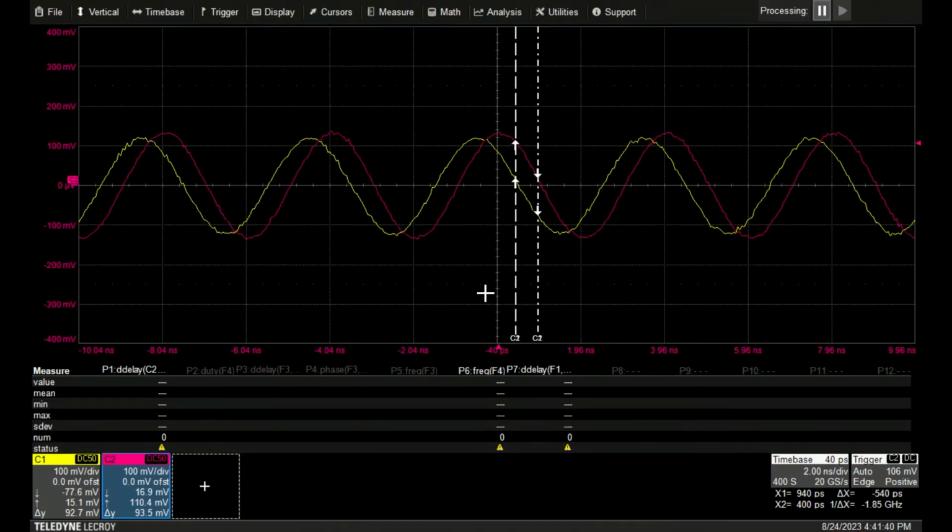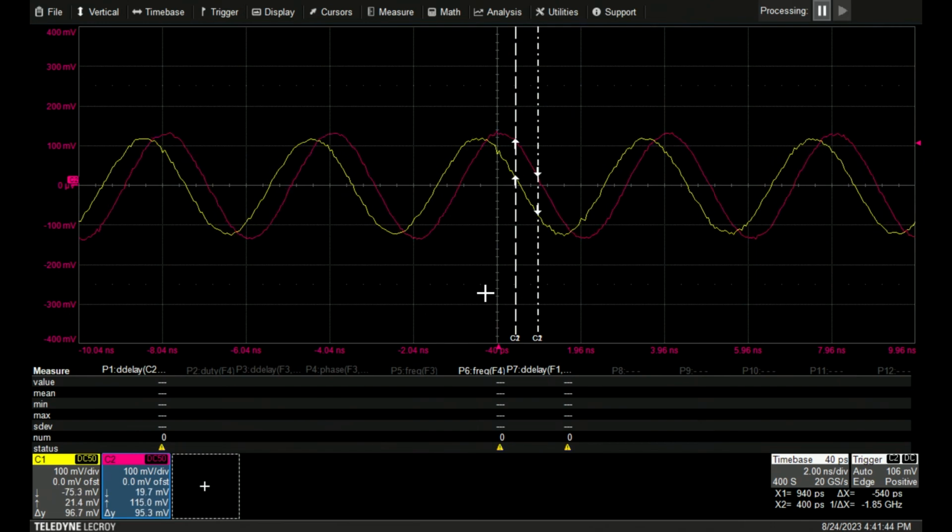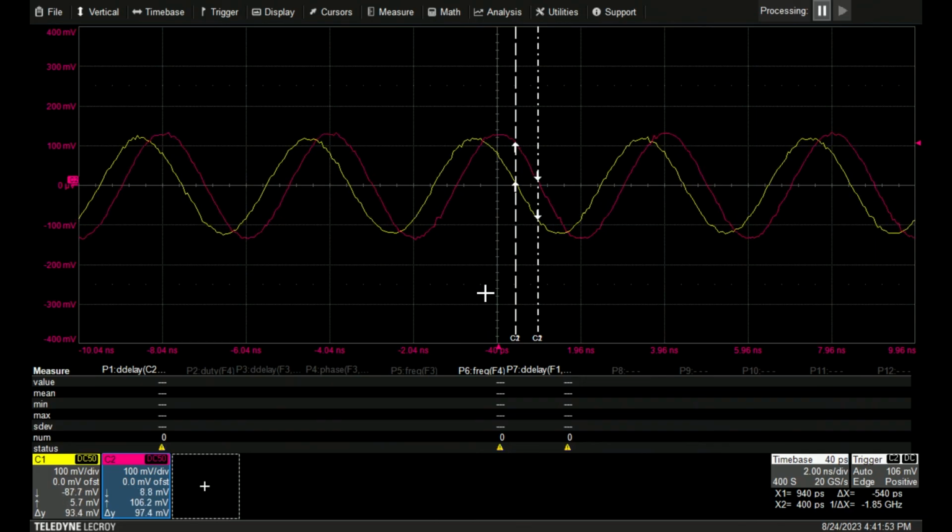Open the pattern generator and configure the desired pattern. Now we can start to configure the signal generation. In this video, we will perform a measure in the following configuration. The two DAC outputs at 215 MHz for sine wave generation. We are using a low frequency so we can better see the steps performed to align the signals. In a real application case, you can use every frequency reachable by the EV12DD700 to generate your signal and perform alignment using the same steps.